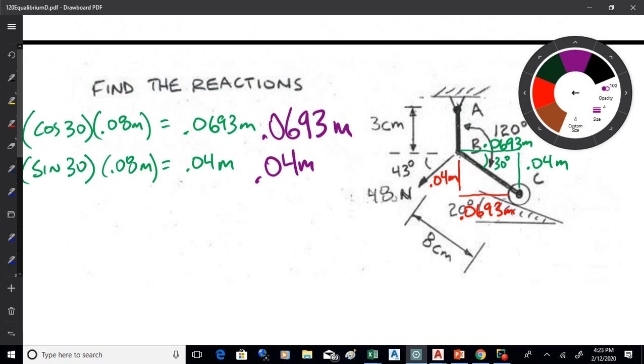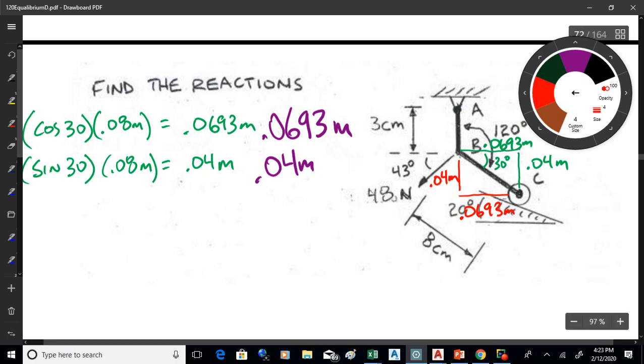Now, the reason I'm doing this, or why I would suggest doing it, is once you have your free body diagram here, of course, I want to generate moments. Now, the way we've done moments, and a common way to do it, is you take the force, break it into x and y components, and then multiply it by x and y moment arms, okay?